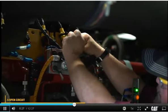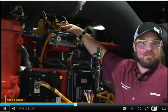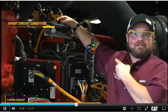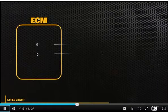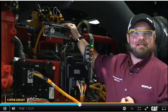All right, now I started out with a -5 code, which we said was most likely an open circuit condition. Now I've made a short circuit condition. Now we can go through and run that solenoid test again and see if the ECM should see that we've made this short circuit here. This is going to tell me if I've made a short circuit here and now the test tells me, hey, you got a short circuit on the end of your harness.